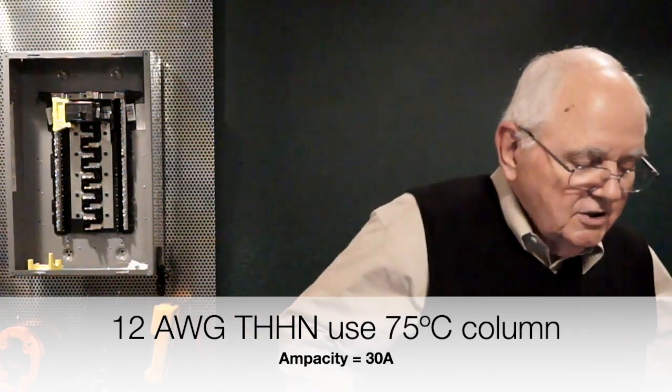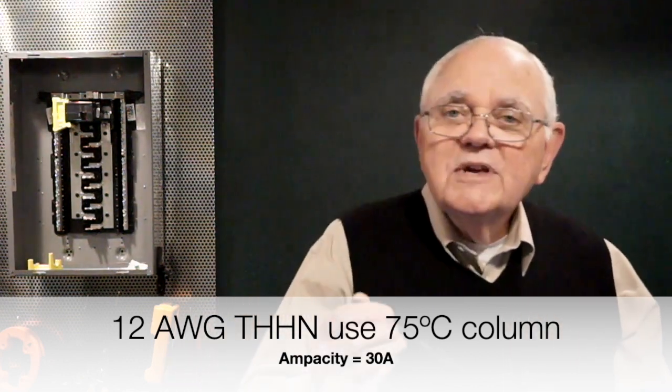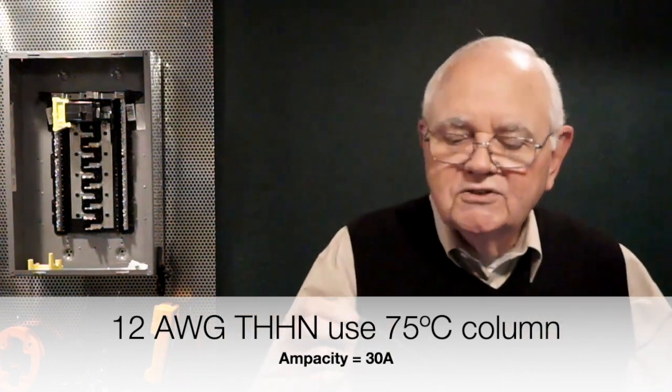So this can safely carry, in an ambient temperature of 86 degrees Fahrenheit and no more than 3 current-carrying conductors in a raceway, up to 30 amps of current flow, and I will not exceed that 90 degrees C temperature insulation rating on the conductor insulation itself.